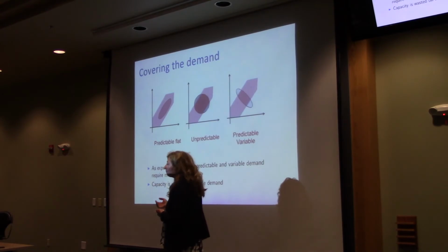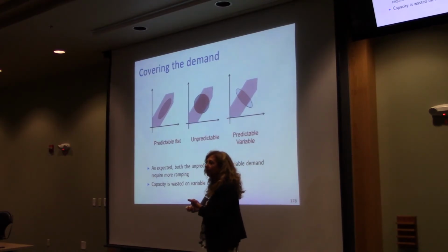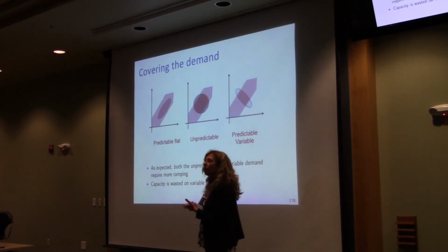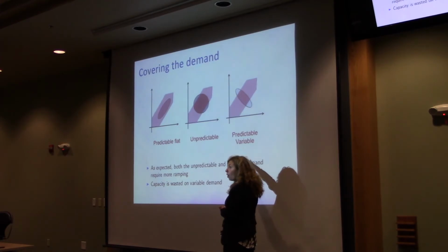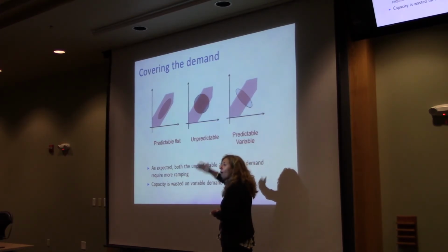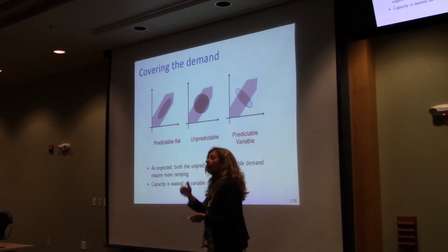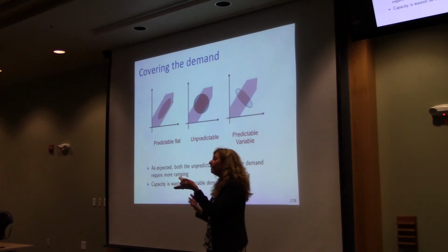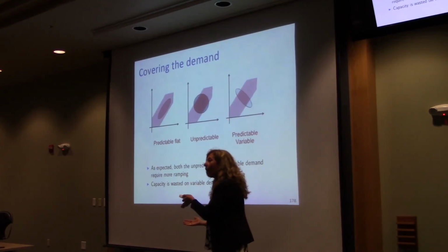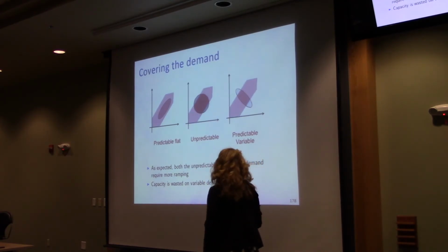It's not flat, right? So what we don't like is both unpredictability and variability. And that's exactly what wind and solar do. The solar power does this to the net demand in the morning and in the late afternoon. It makes it go up and down in a way which is contrary to making it flat, right? So you have these big ramps from up to down in the morning when the solar power kicks in, and before everybody is getting out of the house and going to work, right? And in the evening when everybody goes home, turns on the lights, and so on and so forth.